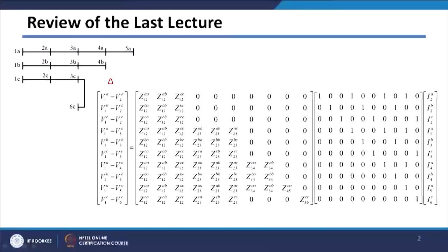In particular, in the last class we saw that using the direct approach based method we can write this equation, which is delta V equal to the BCBV matrix, which has a structure like this and contains impedances, and then this is the BIBC matrix, which, depending upon the topology, consists of ones and zeros, and these are the I node matrix. So, these are basically nodal currents.